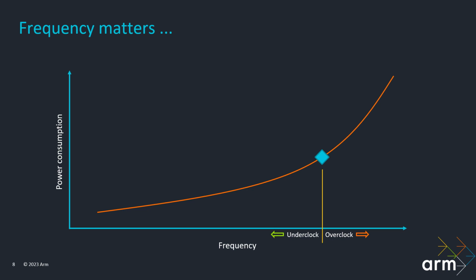If you're a PC gamer, you'll most likely know this from overclocking. Pay an extra voltage penalty and have a bigger fan and a bigger heatsink and get yourself an extra 50, 100, 200 megahertz on your processor. The good news for mobile is that the same effect works in reverse. If we can reduce the workload of the application to a point where we can start dropping the frequency and reducing voltage, we get a V-squared saving working in our favor. So for many workloads, especially for mobile where battery life and thermal is so important, optimizing to achieve an underclock is a technique that definitely pays dividends.